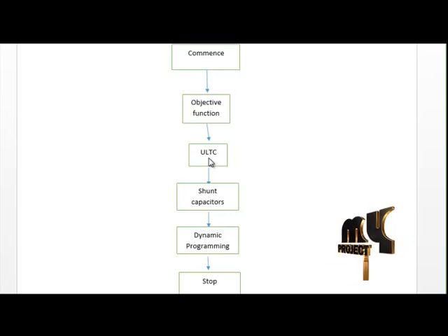A tap changer is a connection point selection mechanism along a power transformer winding that allows a variable number of turns to be selected in discrete steps. A transformer with a variable turns ratio is produced, enabling stepped voltage regulation of the output. The tap selection may be made via an automatic or manual tap changer mechanism.